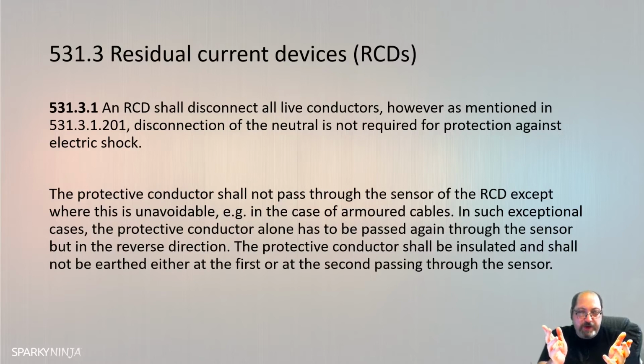That's how circuitry works. Whilst we know that AC changes, it's always in the opposite direction when it's changed. So line goes one way, neutral goes the other through a coil, and when there's an imbalance in current, one of those is carrying less current than the other because some has shot down to earth. That imbalance results in current being induced into the coil, and then it picks it up as an RCD. What this is saying is, I can really draw this, it'll probably be easy to explain.